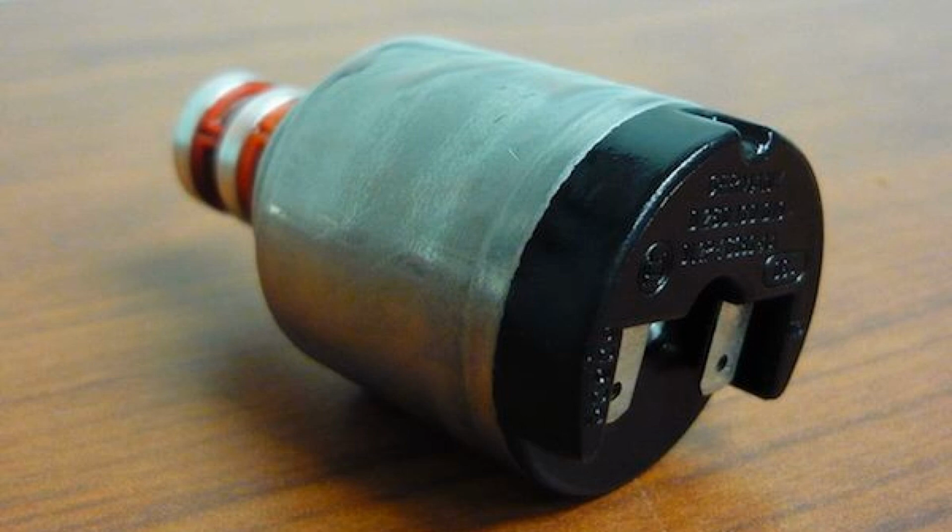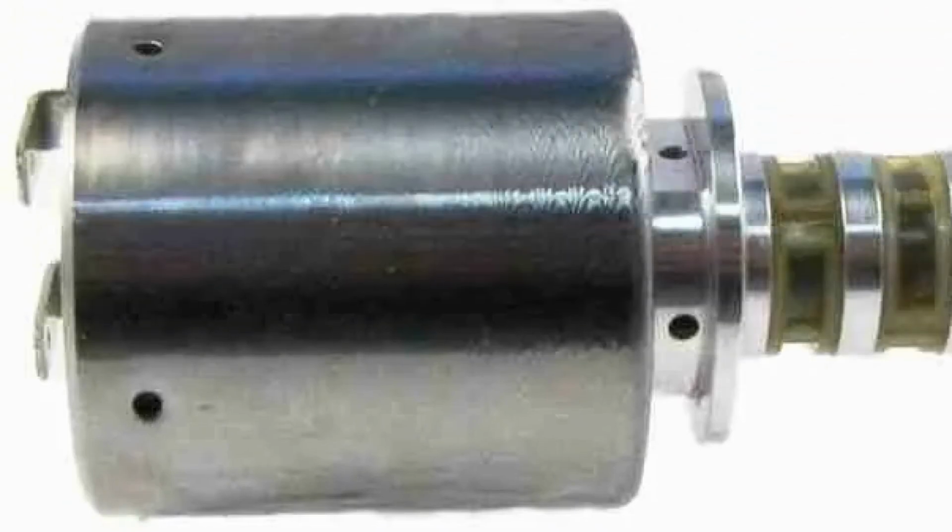You should then carry out a detailed visual inspection to check the condition of the wiring for obvious defects. Check the connectors and wiring for the transmission pressure control solenoid valve, transmission pump, and PCM. Depending on the configuration, the transmission pump can be electrically or mechanically driven.